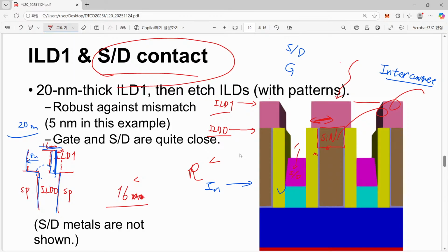So the details are quite complicated, of course. However, please note that that is directly related to our effort to reduce cell area. Please understand, this is nothing related to the intrinsic device. The intrinsic device is already done in our FEOL stage. But by changing where we make this kind of metal interconnection, not exactly metal interconnect, but MOL layer, we can significantly reduce the area of our standard cell.